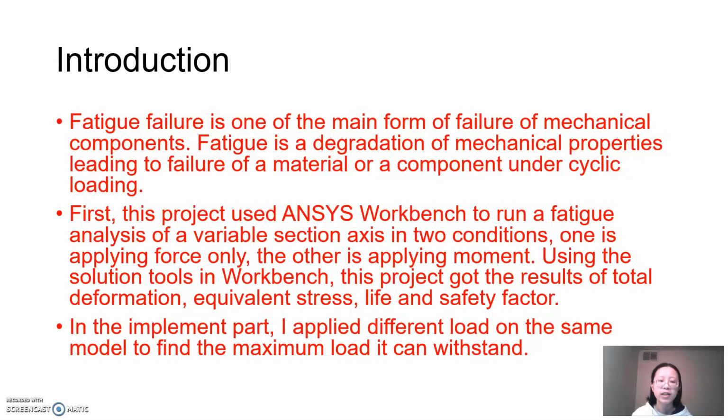Introduction. Fatigue failure is one of the main forms of failure of mechanical components. Fatigue is the degradation of mechanical properties leading to failure of a material or a component under cyclic loading. This project used ANSYS Workbench to run a fatigue analysis of a variable section shaft in two conditions. One is applying a concentrated force on one end of the shaft only. The other is applying a moment on one end of the shaft.